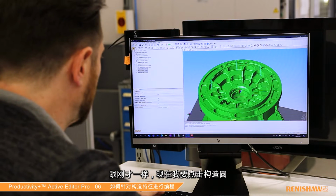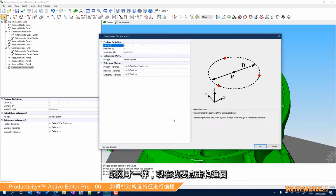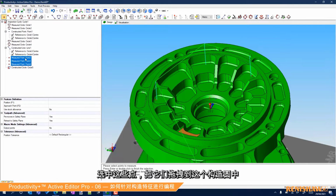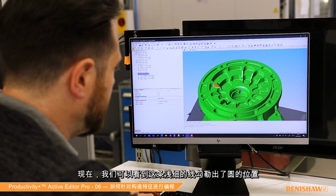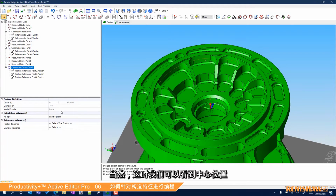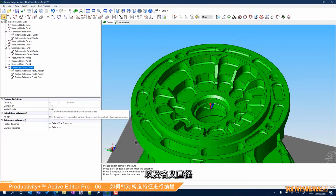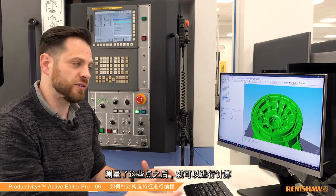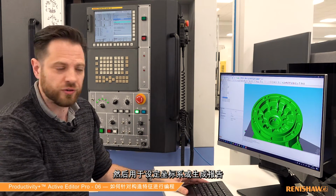And as before, I'm now going to hit the constructed circle, close that dialog, select those points and drag them onto that circle. So now we can see again this faint line that outlines where that circle is. And of course what that's going to give us is our center position, and it's also going to give us our nominal diameter. So when these points are measured, that can be calculated and then again set for a coordinate system or reported on.